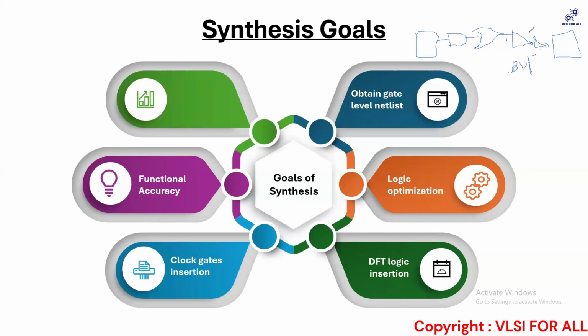Now the output was 0, and now the output was 1. I'm giving it a name, that this inverter was 3. Now, by mistake, it can happen, you made the change from an inverter to a buffer. Instead of turning this inverter from drive 2 to drive 3 strength, you made it a buffer of strength 3. So what happens? Now the output is 1. Now it is not an inverter, it is a buffer.